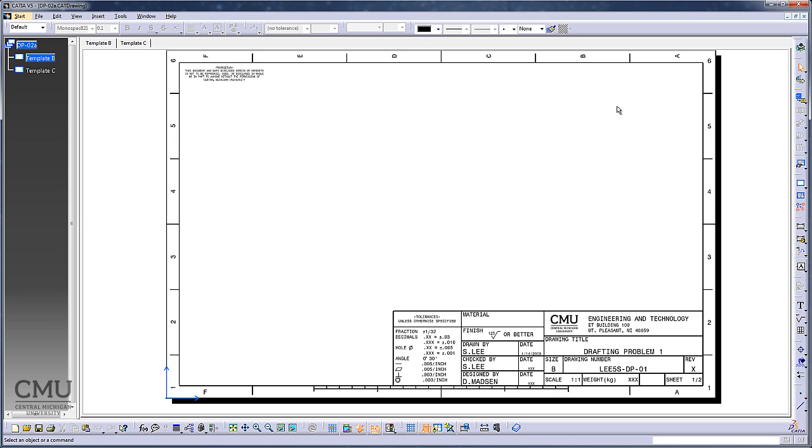And we have the 3 features actually: the datum L, flatness 0.005, and parallelism 0.008 based on the datum L. Those 3 features are showing in the right side. So I need 2 views.